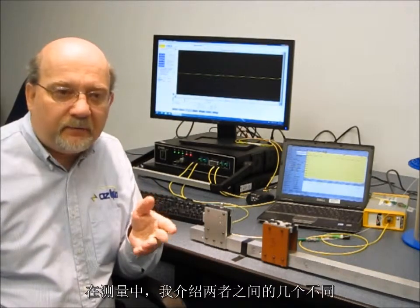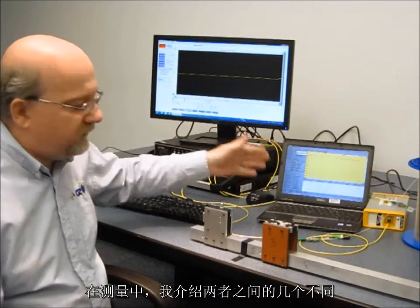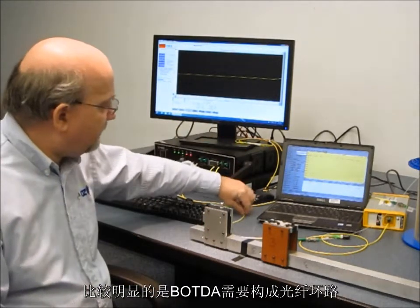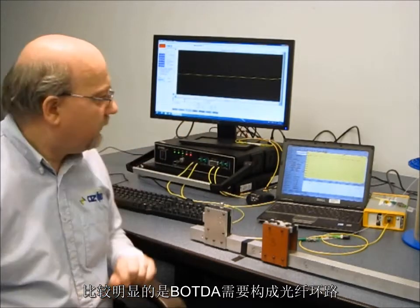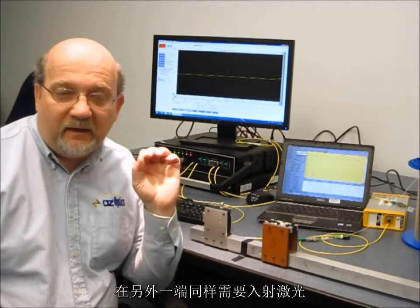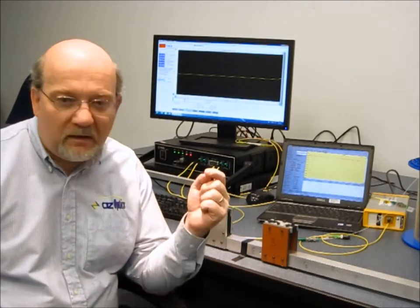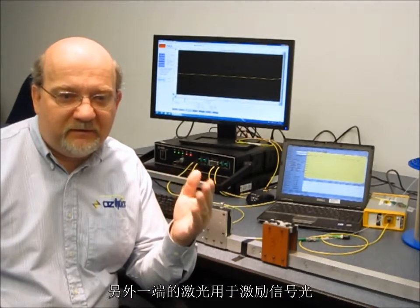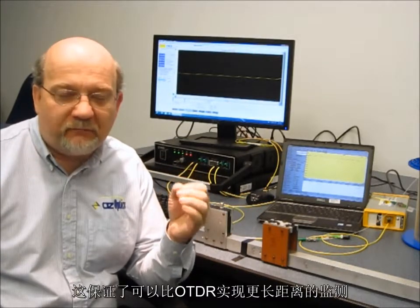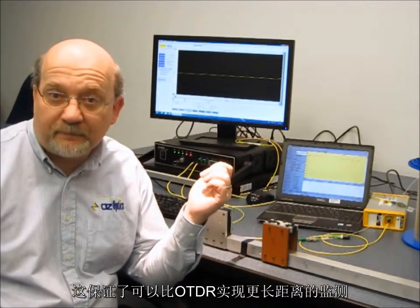While we're measuring the data, let's talk about a couple of the differences between the BOTDA and the OTDR. One critical difference is that we actually hook up both ends of our fiber to our BOTDA system. Okay? And we are launching light in the other direction. So light is traveling through both directions of this fiber. The light in the opposite direction is being used to amplify the signals. And this allows us to make measurements over a much longer length of fiber than what's achievable with this OTDR.